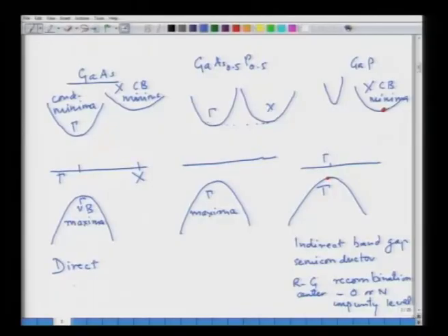And as we have seen, through some recombination process we can sometimes even use an indirect band gap semiconductor to get light. So, this is one way of trying to change the emission. One way of changing band gap is the composition, and 3-5 semiconductors are wonderful for this because they have complete solid solubility in each other. So, you can change composition and go all the way from 100% gallium to 100% indium or 100% aluminum, and change the band gap as well as the lattice parameter.